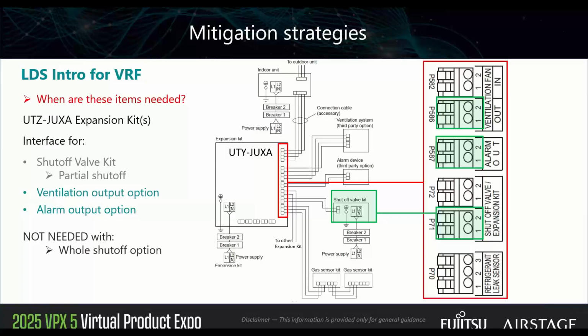And I will mention that those of you that are familiar with VRF know that our other external outputs are 12 volts DC with a max holding current capability of 50 milliamps, of which our typical RIB relay works perfect, the third-party RIB relays. So we could use a RIB relay to initiate a third-party ventilation sequence upon a leak event, for example.